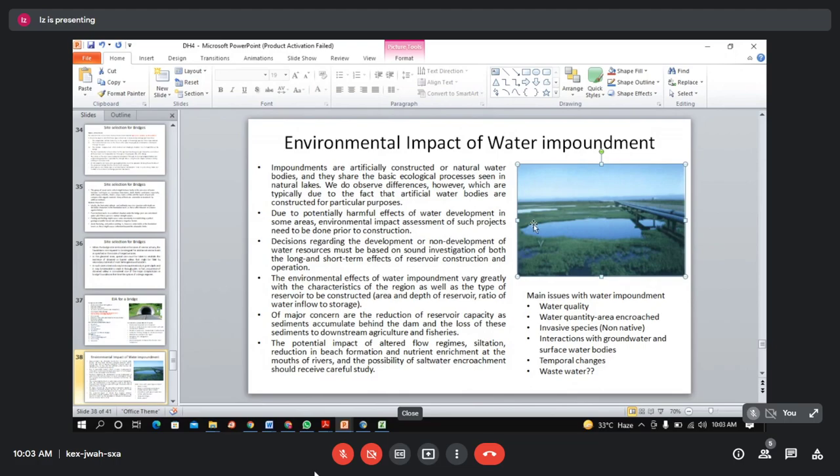Whether there is a chance of this water impoundment being used by some other entities, I mean both in positive or in negative way. Negative way, as I just explained. Positive means okay, this can be used for storing water for some time by treatment plant, right? That is valid. Okay, so treatment plant can take this amount of water in the time of water deficit, right, and can purify and use it for the city for the household supply, but they should not do the reverse. They should not throw their wastewater and use it as a wastewater dump.